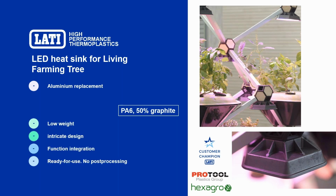We selected a material which is a polyamide 6 with 50% of graphite. This allowed to obtain a part which is significantly lighter compared to the aluminum one. Then it also allowed to create an intricate design, something which is more similar to the geometry they wanted to have. You can imagine the previous heatsink in aluminum was a simple geometry taken from the market. In this way, it was possible for them to design the part to be as they wanted.